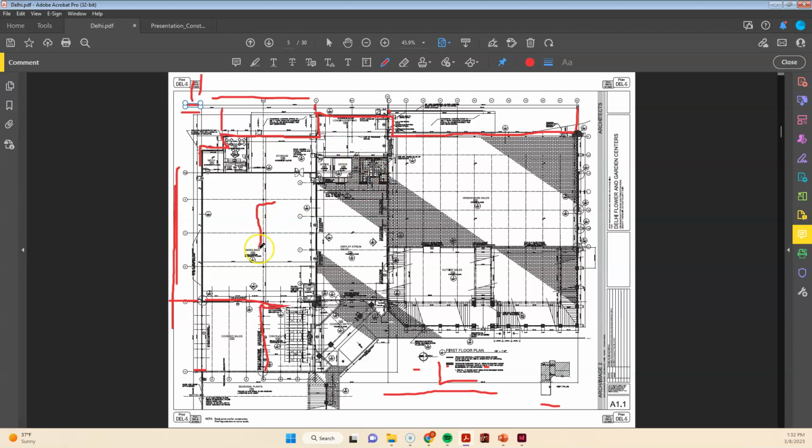Overall big dimensions and column spacing, I could see even from a distance, running through some rooms. The next important thing, also from this distance, I note the hatches. These are brick hatches. That is not this. These are wall types. These are hatches telling me what's on the floor actually, something you would expect to find on a floor plan.